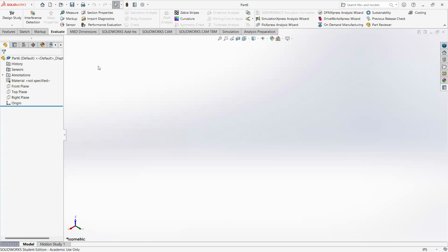I'm not ashamed to admit that in my head, I never really converted to metric. I still very much think in imperial. So my native SolidWorks environment is in imperial units. The first thing I would recommend would be to change that for the part you're working on, especially if the test tells you that that's the unit system. That's fairly easy to do, and I don't want to change it for my whole environment. I want to stay in imperial units.